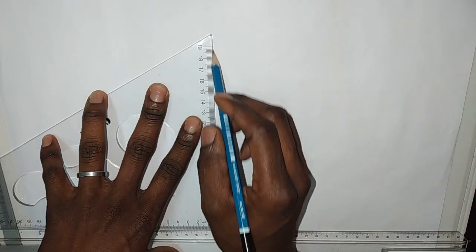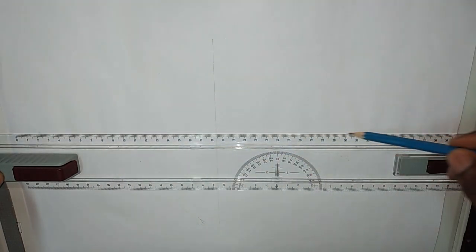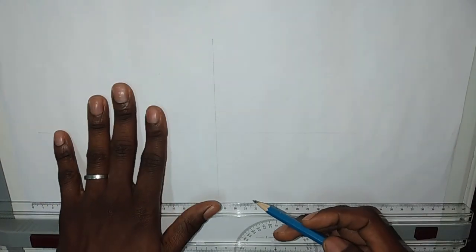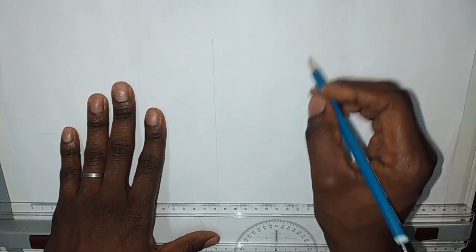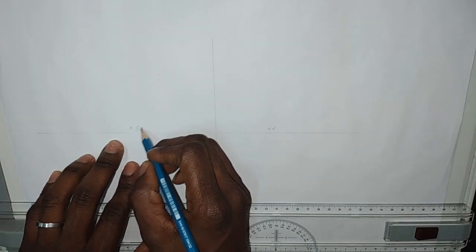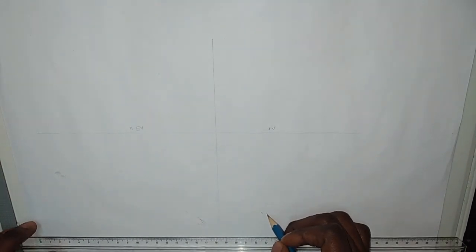If we start by getting our axis, so as seen, we have a right end view, which is going to be positioned at the left side of the front view. The front view is going to be here. Our right end view is going to be this way, and our top view is going to be down here.